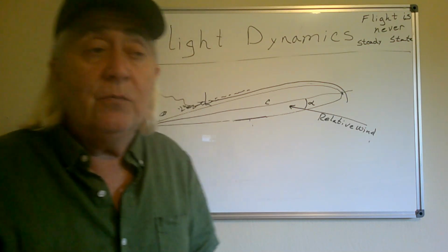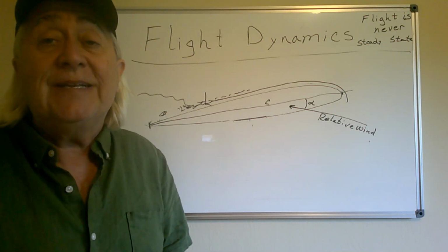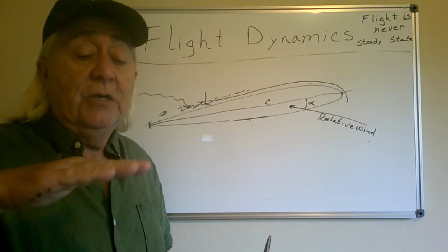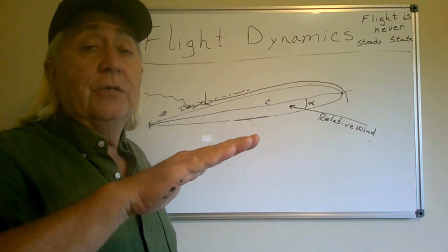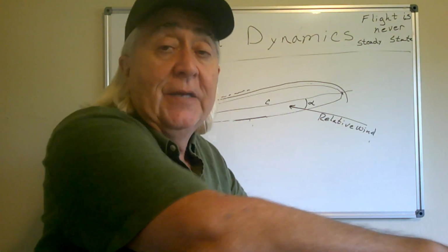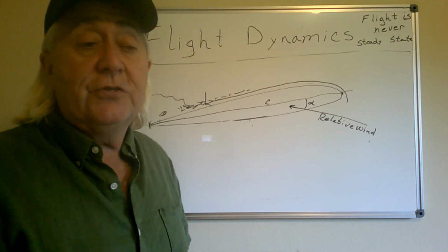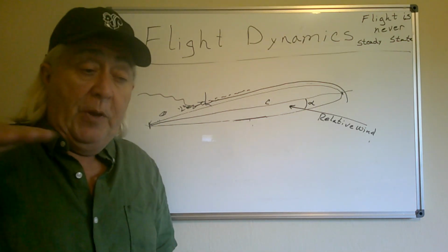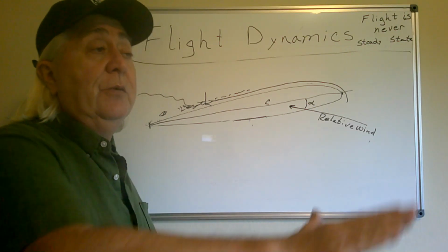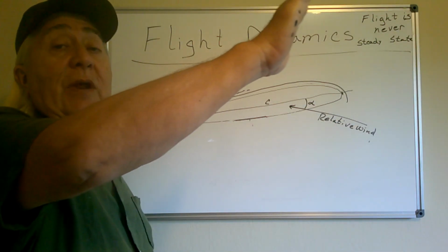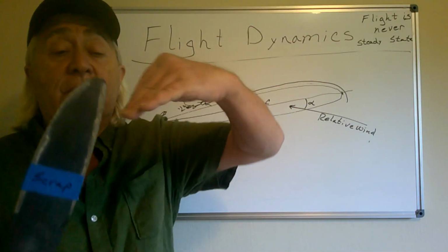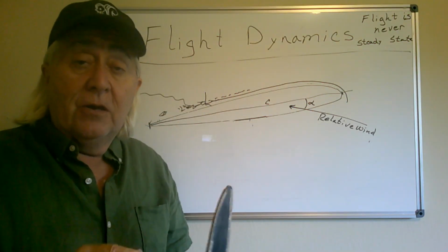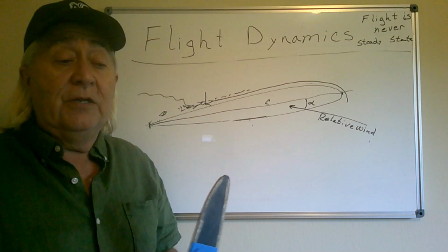In fact, in the gliding world, we practice these, and they're called accelerated stalls. We have stalls that we practice where we go along and we just slow it up, going slower, slower, burble, burble, burble, put the nose back down, get back to flying. That's the start of a stall. We have other stalls that we practice where maybe we put down the nose a little bit, pick up some speed, and do a big pull up like this, and wait and wait and wait until that relative wind is at the appropriate angle for a stall,